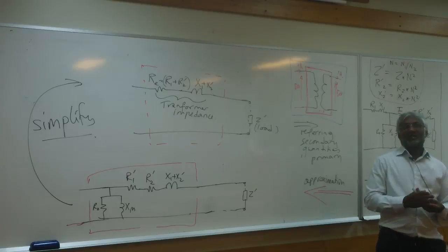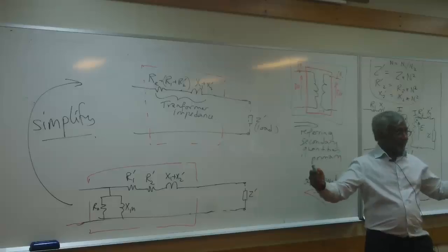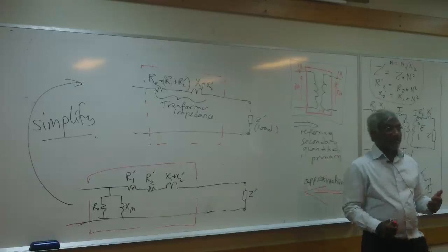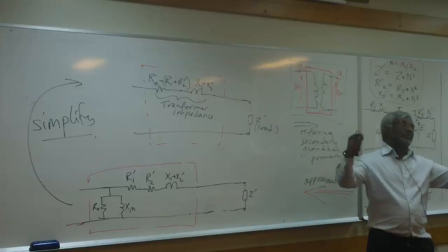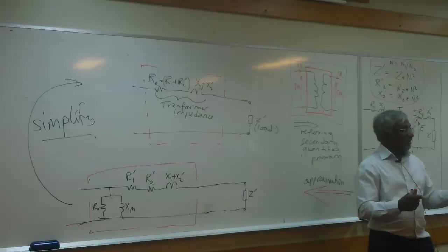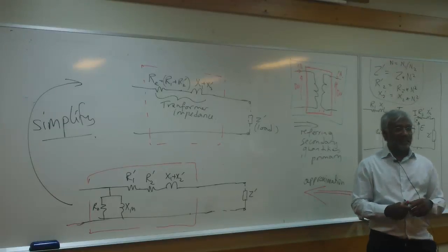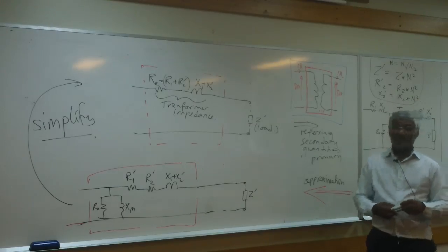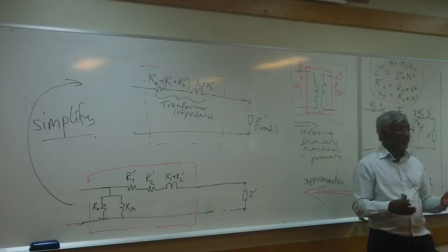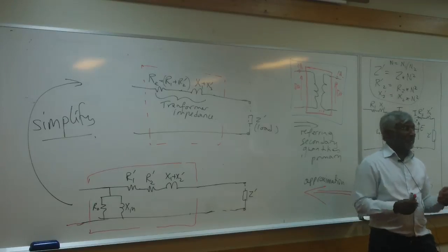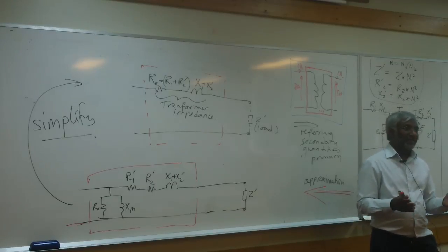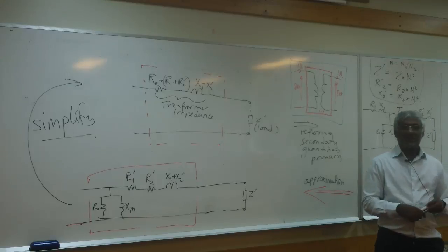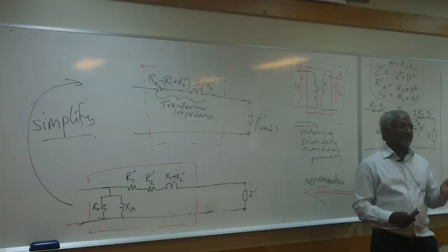But normally, for continuity of supply, especially if it's a big load like the city of Toowoomba, you would like to have redundancy there. So there are two reasons for paralleling of the transformers. And when you parallel, if you want them to share equally or share according to their ratings, then you would adjust the impedances. Now, what's the other reason for maybe wanting to raise the impedance?